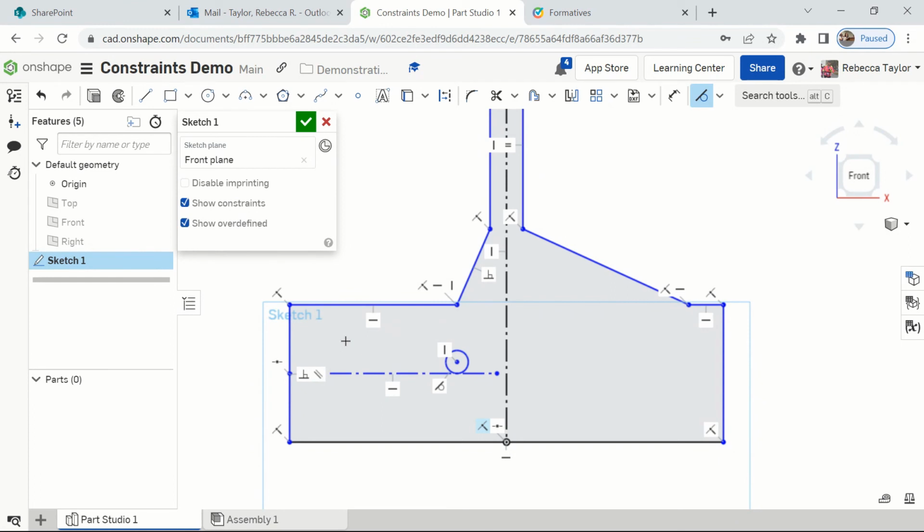All right, now draw a circle on the other side in a similar place. So I'm just going to come over here and we'll do that, okay? Whoops, only one circle, there we go. And then what we're going to do is constrain the second circle to be symmetric to the first. And there's a big note in there.